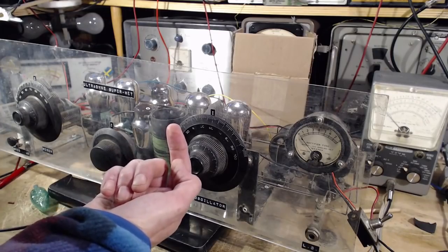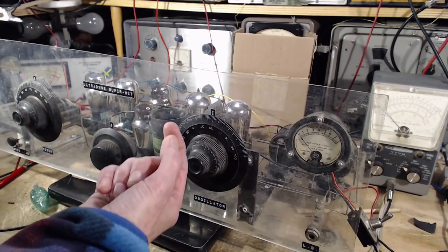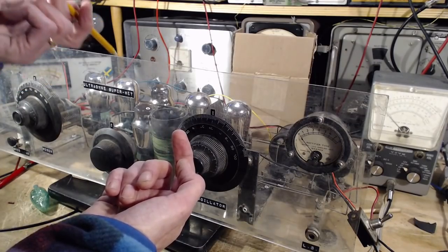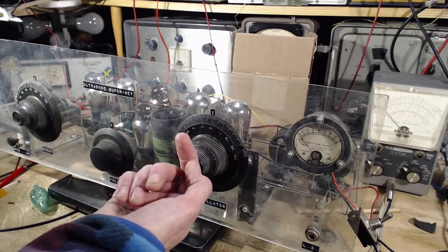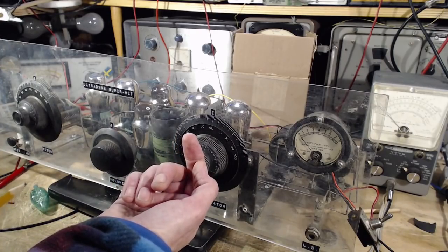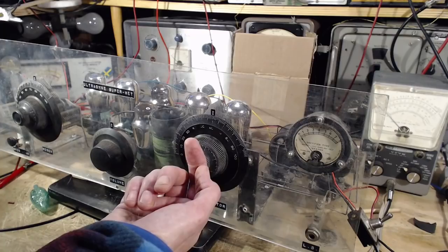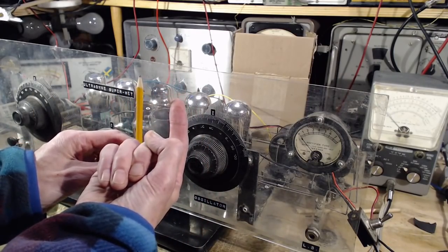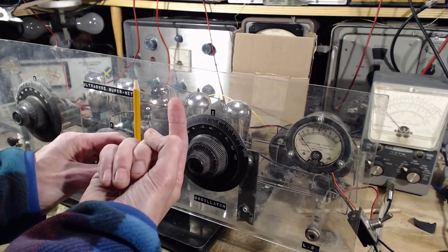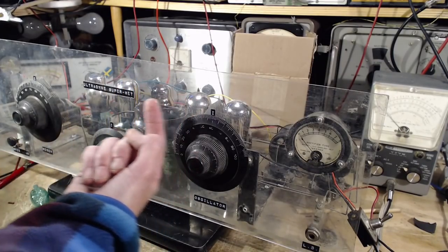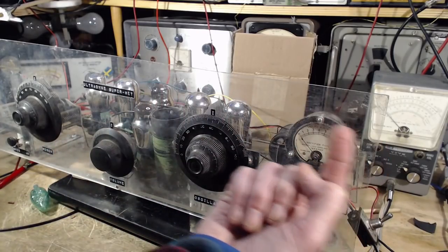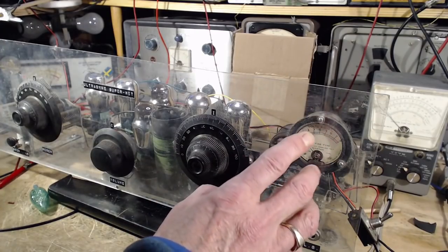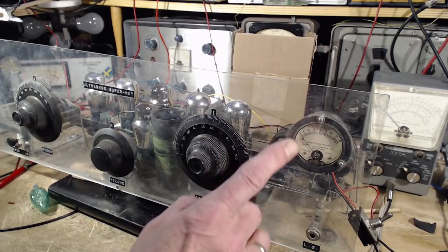But really, if the IF is only 100 kilohertz, which it appears to be something like that, 75 in fact, then the local oscillator is running just a little ways away from the tuned signal. So you have your tuned signal here, you have the local oscillator here, 100 kilohertz in between. And so this local oscillator pretty much sweeps through the AM band. And that's what that resonance was doing. It was sweeping through the AM band. Or was it actually sweeping 100 kilohertz higher?